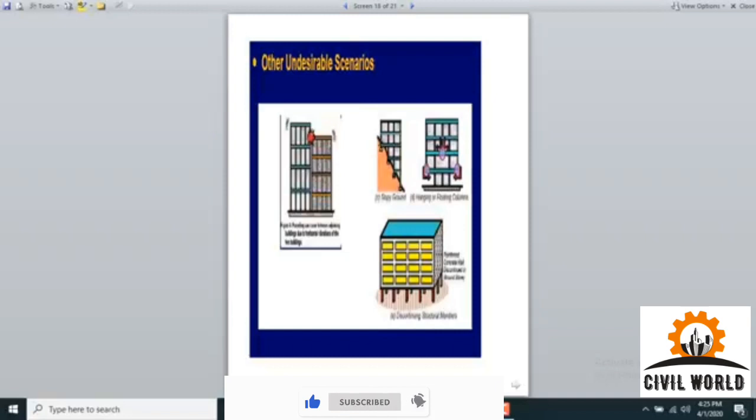So it would be better that we should have converted this contour line into a horizontal ground by introducing a cut here and converting this structure into two parts, one like this and the other like this. So on the basis of that, these two foundations can be laid at one level, while these two foundations can be laid at the second level. So that would be more stable form as compared with this one. This is not the ideal case. It can cause a sliding with a slight magnitude of earthquake.